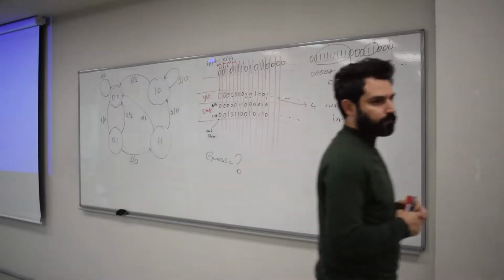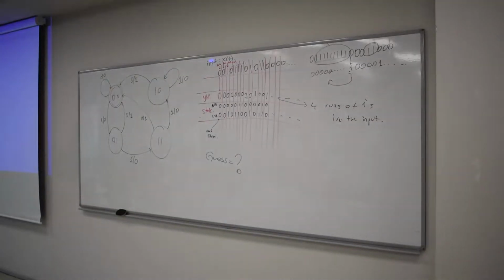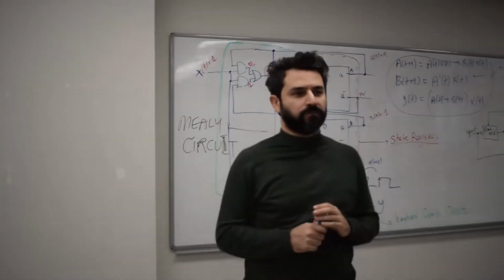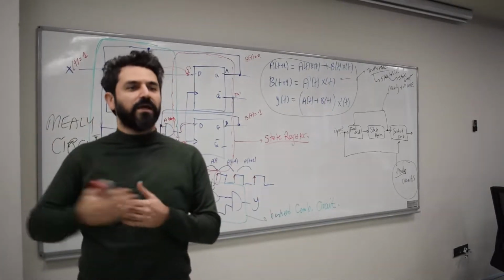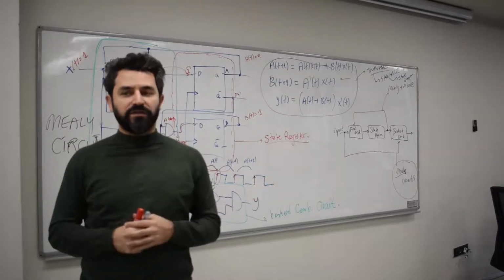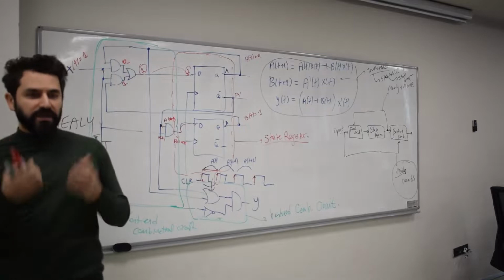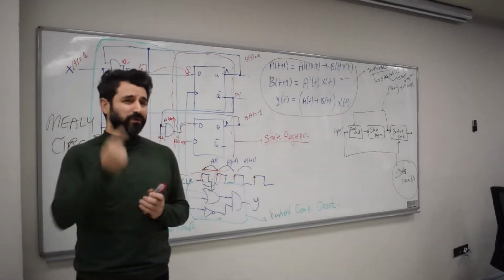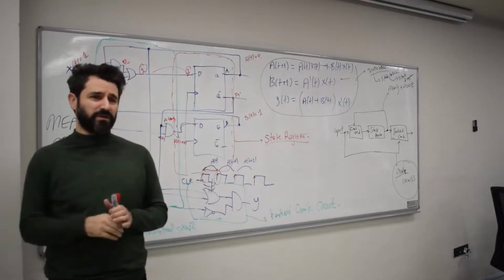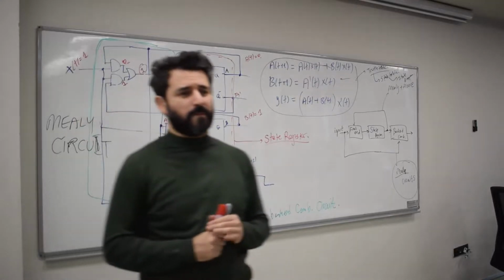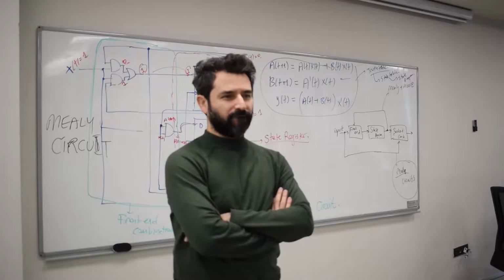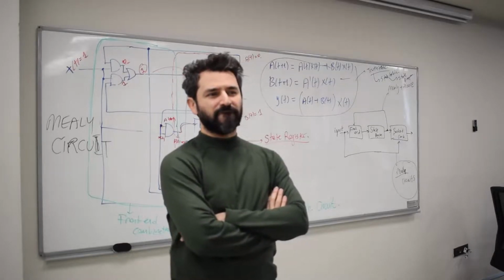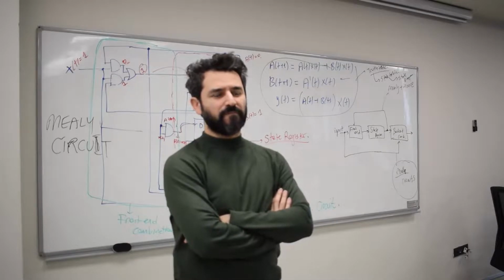Okay? If we had 1,000 runs of ones. Yes? Would it be just 1,000 ones in the input? Because we would create the same thing. The input can have 1,000 consecutive ones in 1,000 places. Okay, digits actually. So therefore, it is possible, and this circuit will only output a single one at the end of that 1,000 ones. So how would you know if we need to make an error out of this? Error? Yeah. What type of error? If we have 1,000 runs of ones, how do we know if we have 10,000 ones in the input or not? How do we determine that this could be a communication error during the communication?